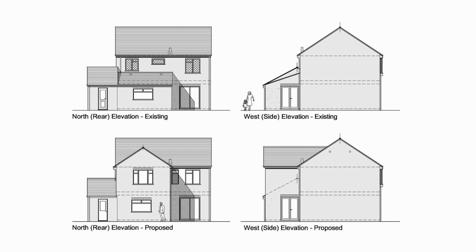These particular elevations, to me, don't have as rich of a set of line weights. They're a little bit more stark. If you look at the lines of the roof plane, for example, they're a little heavy. They don't need to be that heavy. They draw too much emphasis to the roof and or too much emphasis to the shadows. There could be more diversity in these line weights. And I think that would make it a little bit better as a drawing.